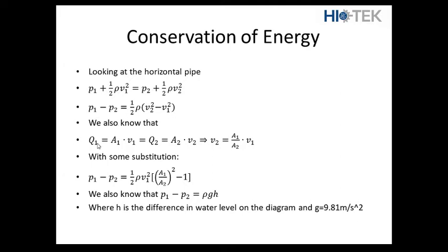So we don't have a vertical component again, so we're sitting with that equation we came out with the first time, in the previous section. And we also have Q1 equals Q2, and if we solve this and look at V2, which is the velocity in the neck, we get it as a ratio of A1, the area of the larger pipe, divided by A2, the smaller area, times the velocity in the larger pipe.